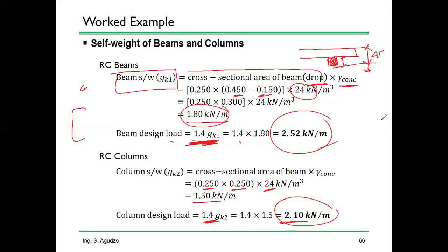Okay. Any question regarding calculating the self-weight? Because when you are designing, don't assume that the self-weight is 0. It is a comfortable assumption we do just for classroom, but in design, the beam itself has a weight, so cannot be assumed to be 0. I believe you did same in your steel design, design 1. That you calculate the self-weight of the steel.